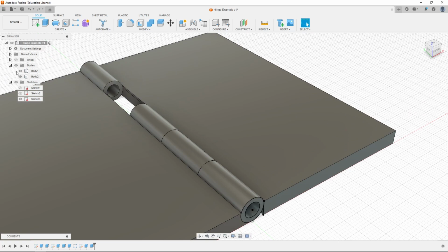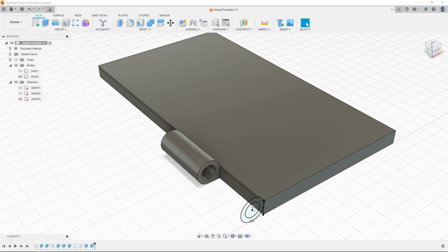So again, we have some choices. I'm going to hide body 1 for a moment. Could I do the same thing? I could offset by 20, 40, 60, 80, and then go 20 across, and that would be okay as well. Or I can simply maybe try using that rectangular pattern to make this whole object go some amount as well. So we'll do that, and that's what we did in our last video, so we'll do it here as well, just to be consistent.